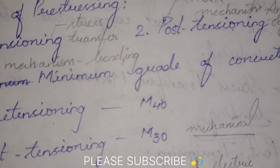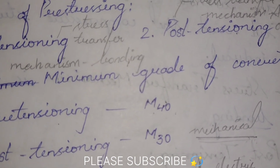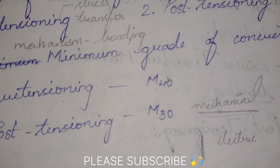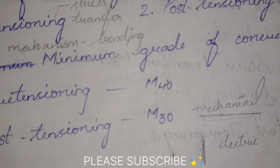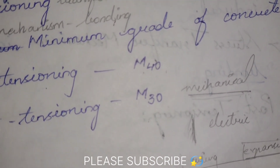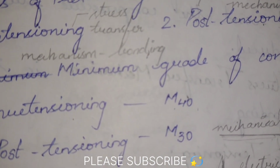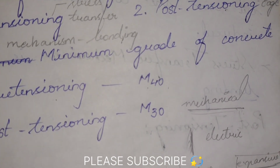Next, let's see the chemical method. We know some expanding cements, right? The degree of expansion is controlled by using some curing conditions. So here we'll fix these curing conditions and use this expansive cement. Initially we will pour this cement and leave it, so it will get expanded. Here the expansion is restrained, so it will induce some tensile forces in the tendons and compressive forces in the concrete.